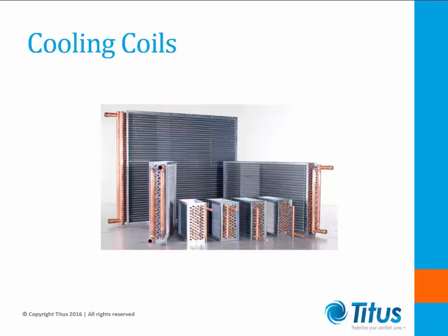The depth of coils relates directly to the latent capacity and fan power. Minimizing the number of rows in a coil would decrease coil pressure drop, but at a penalty to coil latent capacity. Generally, we would expect to see 4 to 6 row chilled water coils used to handle standard office air handling equipment, but would expect to see 6 to 8 rows for an outside air application. As the depth of the coil grows, so does the difficulty in cleaning the coil.